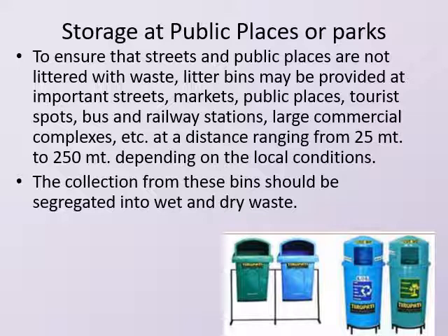So litter bins or community container bins may be provided at important streets or junctions of important streets, near markets, public places, tourist spots, bus stations or railway stations, large commercial complexes, etc., at a distance ranging from 25 meters to 250 meters depending on the local condition.